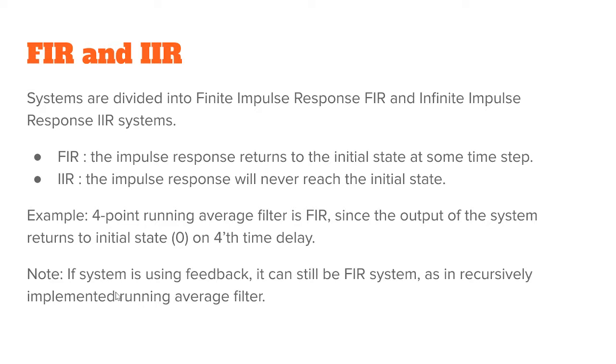Based on the impulse response, we can actually divide these systems into two categories. One is the finite impulse response systems, meaning simply that our output has an ending. If you feed in an impulse function, does the impulse response actually go to zero at some point and stay zero? So that means that our impulse response is finite.